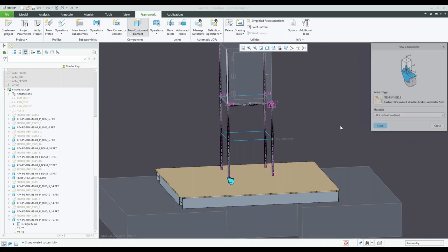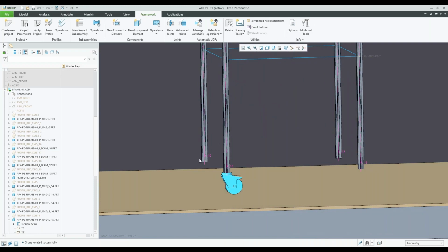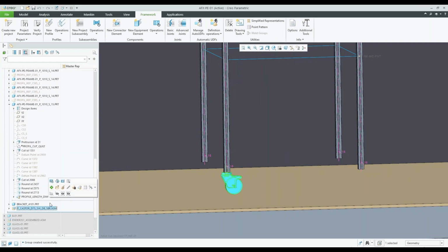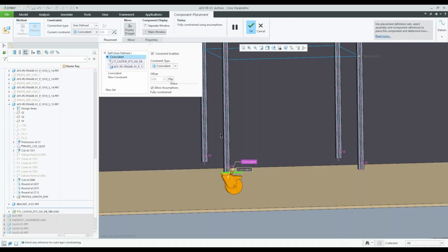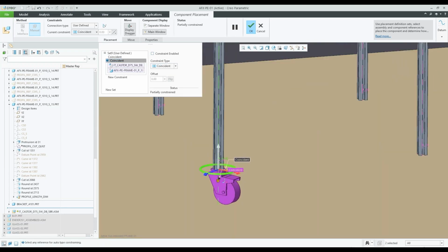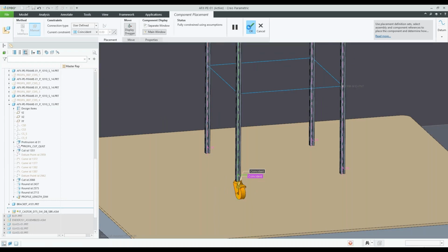And just like any other part that you've assembled in the past, you could adjust the position. So if I wanted to, I can just find that wheel. I can edit definition on that. Maybe I want to turn it. So you can see that I have the axis constraint here, right? I can deselect the constraint enabled, and I can just rotate this to position it where I want it like that. Okay. Re-enable the constraint.